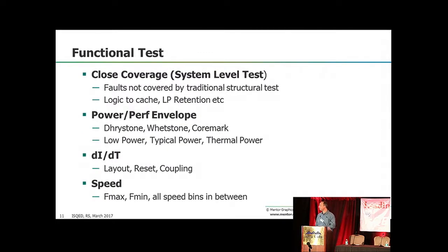Functional coverage. So functional coverage is your traditional approach: you run some programs, you write some C code, some assembly. It's always been very difficult to do and very time consuming, but if you take a design for test methodology to it and apply test logic, you can still run it functionally, but in a test mode. You don't necessarily have to run it in the same mode that the customer runs it in.